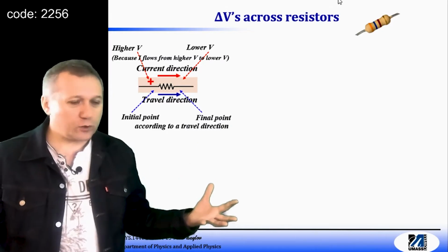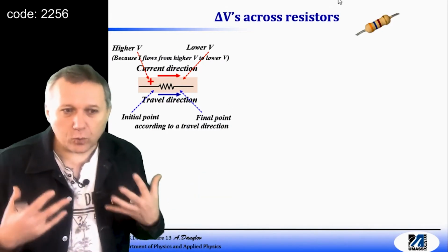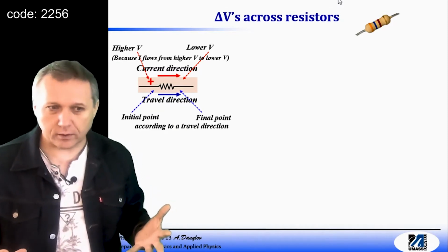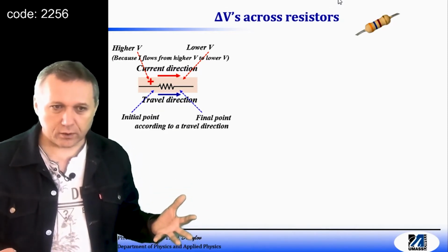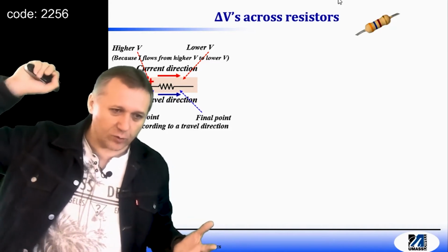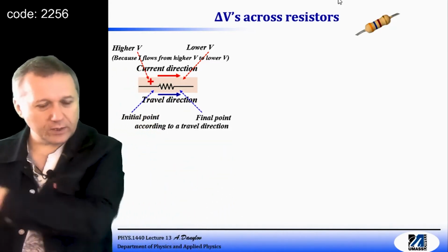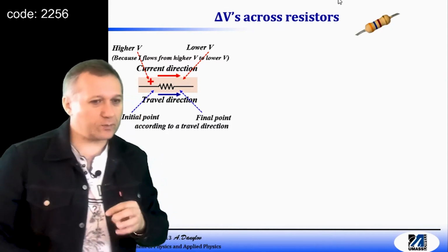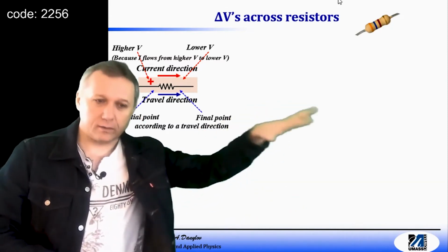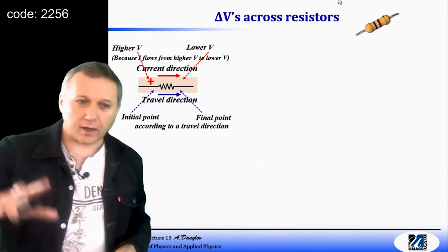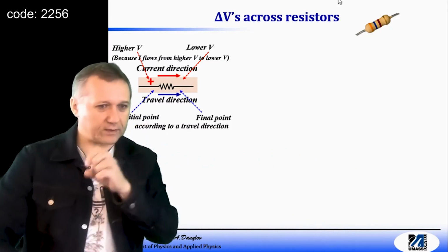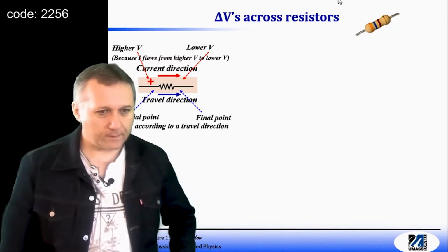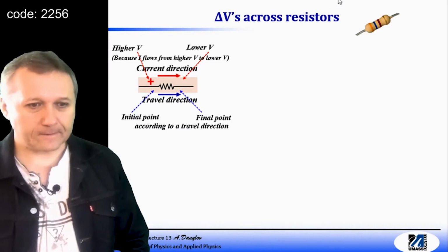Very often you have a multi-loop circuit and there's just no way to tell which current direction is correct, it's too complicated. So every time we just assume this is the current direction or that is the current direction. Then when you solve the problem, we make a statement and adjustments. Current positive, my guess was correct. Current negative, my guess about current direction was wrong, change it. You solve the problem. You are the winner.